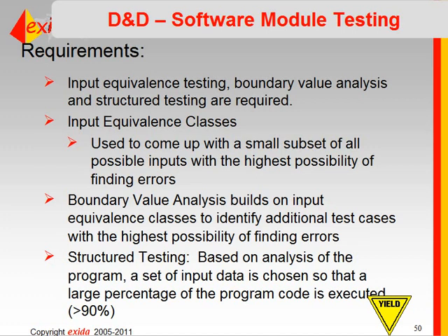And in terms of coverage, the other thing you have to look at is actually all the code in the function. The goal is that all of the code is tested, 100% of it. Although the standard doesn't specifically state a percentage, and 90% is a target that's been accepted. But I would think because during module testing you can use a debugger, you can set breakpoints, various things like that, your goal should be to get to 100%. If for some reason you can't, then 90% is like a fallback target.